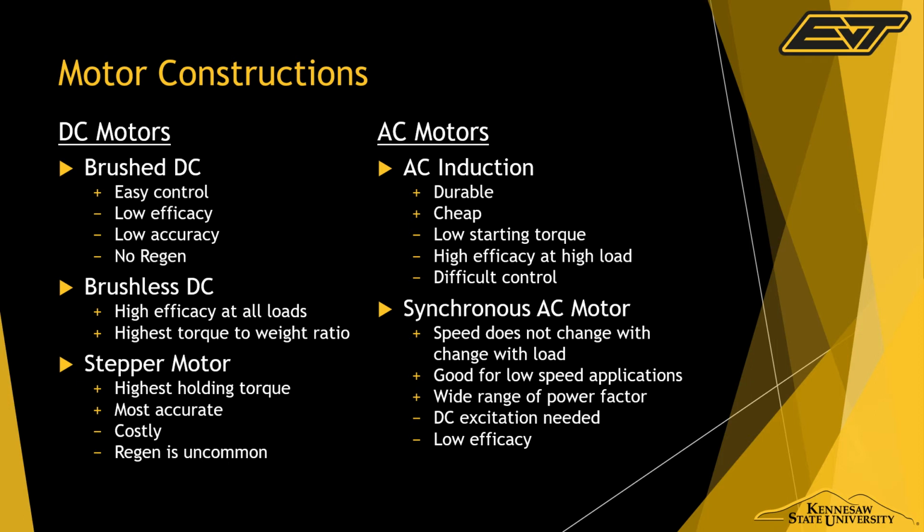Well, that is going to be a pretty large load, and they tend to have a higher efficiency with higher loads, just because of the induction stuff. But for our situation, we have a high load only while we're accelerating. But then as soon as we get to staying at a constant speed, then the efficiency will drop for us when we use an AC induction motor.